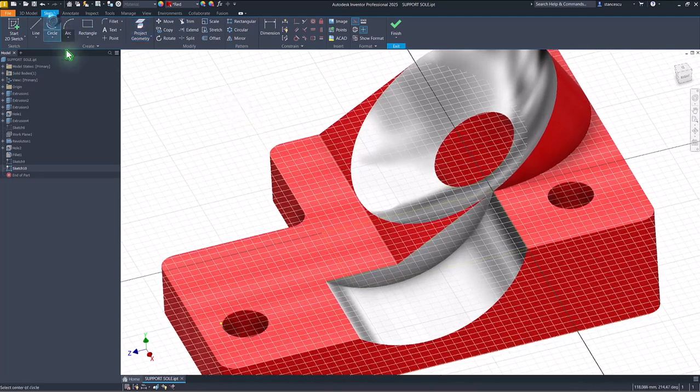Because you want to draw a circle, but you noticed that this is also construction, because this was set. I disable this and I select the circle. I disable also the construction tool. You may want to trim this arc and continue with other entities, but not these lines. Okay.